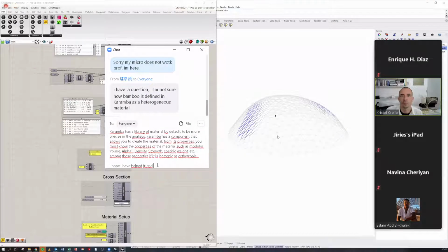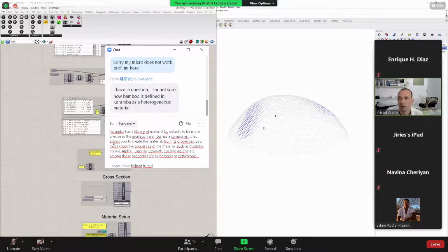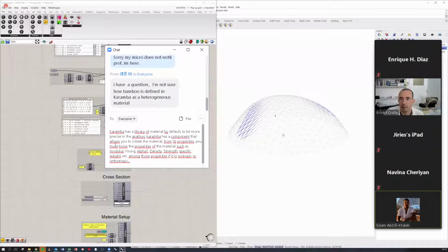Like I know with a steel structure, for example, if you put a high tension membrane on top of it, then the membrane itself can maybe help absorb some of the tensions. But I think that's a rather theoretical thing. And also it can distribute the bending forces uniformly around the bamboo structure. Yes, it can. But there's two reasons why we didn't incorporate that at this point in time. One, we just didn't have the setup to do it yet.